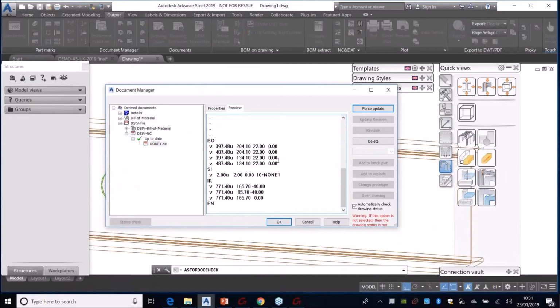So this isn't the only reason why this can cause an error. Of course, there can be issues with the part marks related to the items. It's always important to keep the numbering up to date with your project. But right, these are how you can resolve these issues, is understanding the block references and knowing that the 2 stars associated with the element is identifying that that's the issue or is causing an issue.